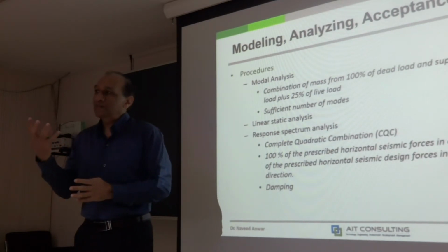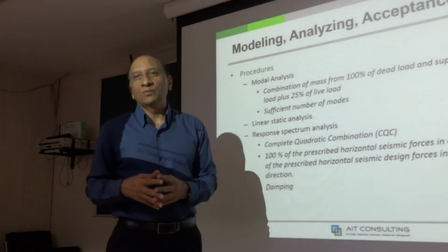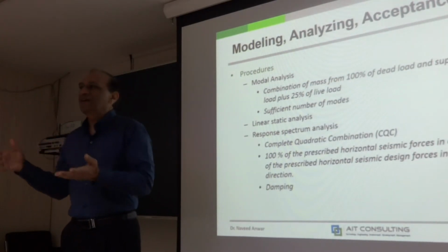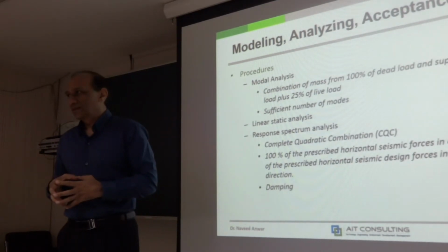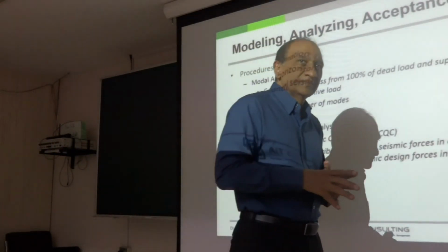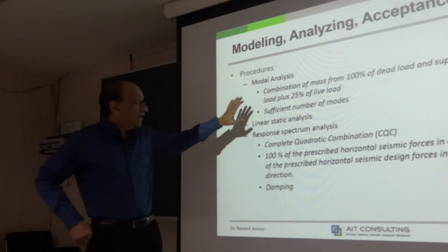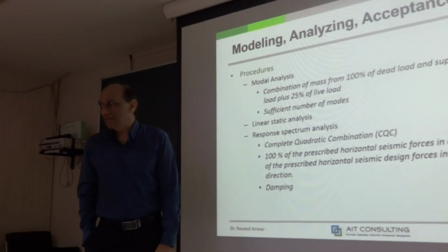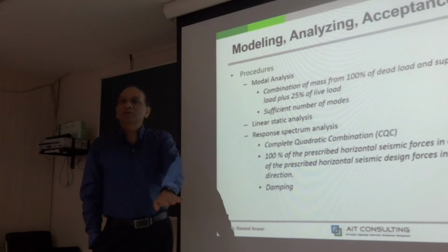But the actual number of modes which are important is that many. So for a 30-story building, about 90 modes should be looked at. Of course, we may finally find that we only need 20 out of that, but we cannot know in advance how many we need. How will we know how many we need? Later. This is just a criterion, otherwise too many things to discuss. We will find a way to determine how many modes we need, right? We cannot know in advance, but we need to do a lot to make sure that we get all.